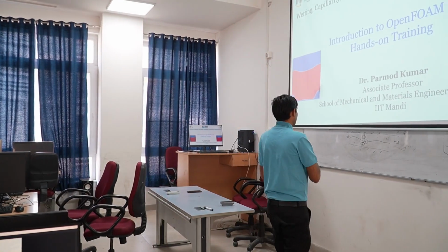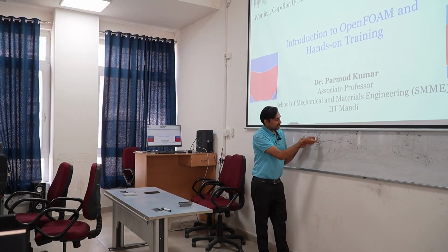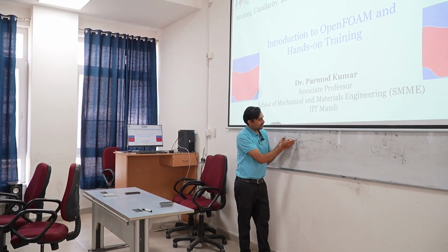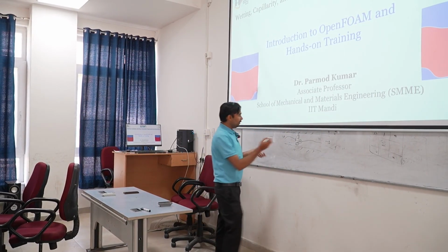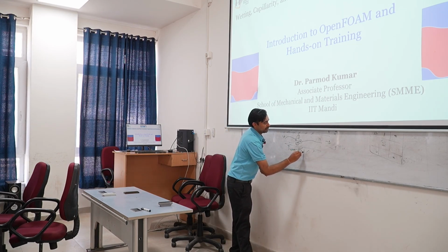So this type of approach, where we separately use the momentum and continuity equations for each phase, and then apply the boundary conditions at the interface to exchange the forces and the momentum, we call the two fluid approach.